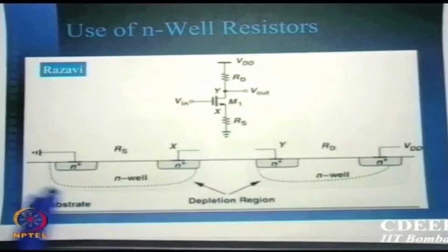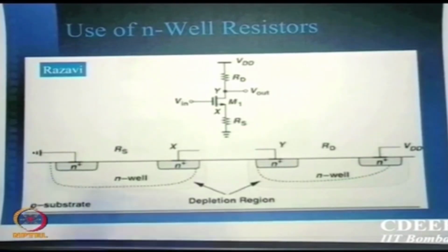If I have an N-well device area there, yesterday I said you start with a P substrate and create a deep area which is called N-well. Well means 5 micron down or 3 micron down, that's why I call it well. Please remember in a circuit only the first half a micron or even lower is the actual surface depth you will use. All devices are within 5000 angstroms. Then you don't need more. Then why do you need so much thickness of silicon? Because it's extremely fragile and to handle it at least you should have some stability.